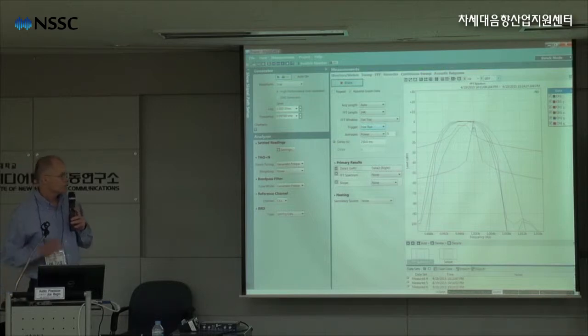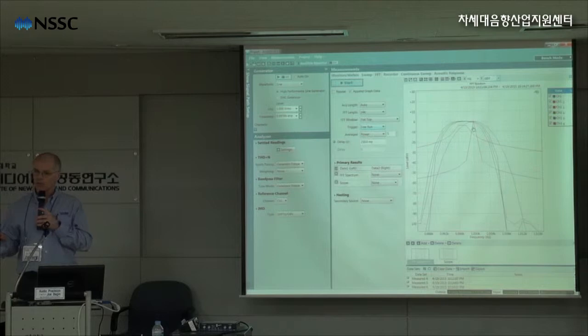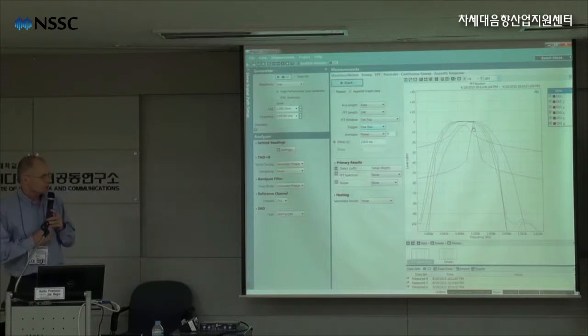peak. So for an application like using a sound level calibrator, the frequency is nominally, say, 1 kilohertz, but it could be off by 1 or 2 hertz. And if you're trying to calibrate your microphone, this would be a good way to do it, because the peak of that FFT gives you a very good estimate of the signal, regardless of where it is relative to the center frequency of the FFT bin. Any questions on that?